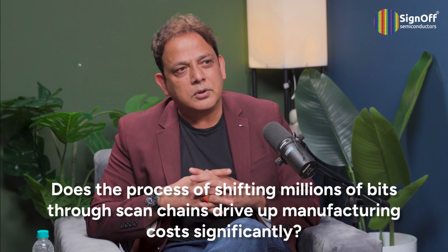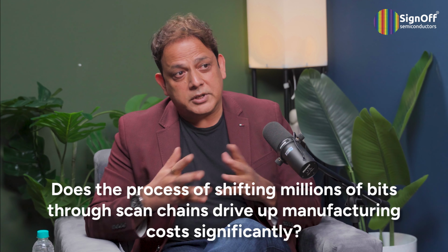So, from a manufacturability and manufacturing cost perspective, doesn't it increase the whole cost of manufacturing, because the testing cost goes up? Correct, Rakesh. So what happens is these patterns, ultimately we are going to run them on the tester. Now these testers are very costly. The cost of the tester per second is very high. Now the more you are holding the tester for testing the chip, it's going to be more production cost for you. So the time taken on testing is a time for the production.